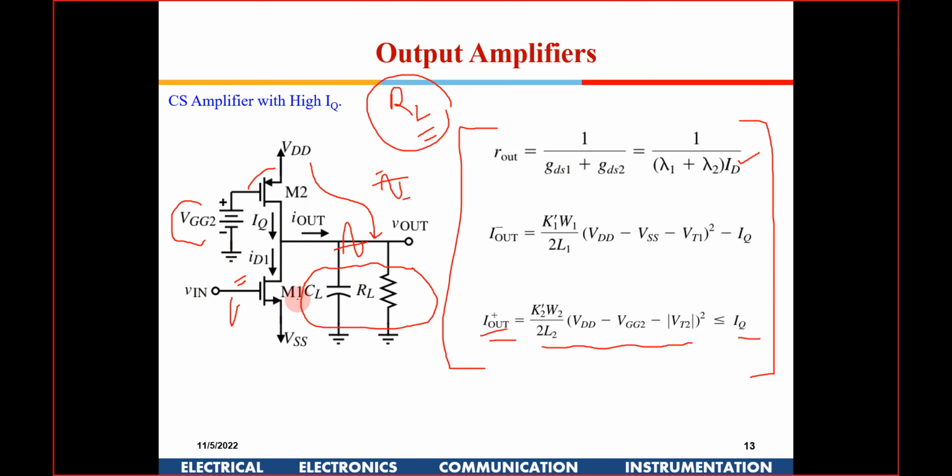No, both will be large, to satisfy these equations. If you don't size these transistors accordingly, then we will not be able to drive these loads at those voltages. And you said RL, CL should be less, right? CL will be large and RL will be less, so we have to cater for that. Yes, that depends on the user requirement. So this amplifier has to be designed for taking large CL and low RL.